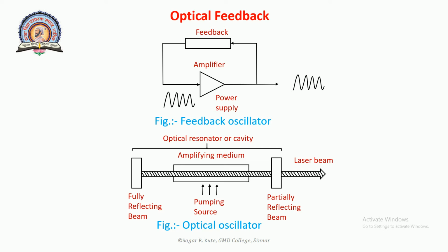When the oscillator is switched on, any noise signal of the appropriate frequency appearing in the input will be amplified. The amplified output is given back to the input, a stable output is quickly reached, and the oscillator acts as the source of a particular frequency. The laser is an optical oscillator in which the amplifier is the pumped active medium. Gain saturation is basically a property of the laser amplifier.